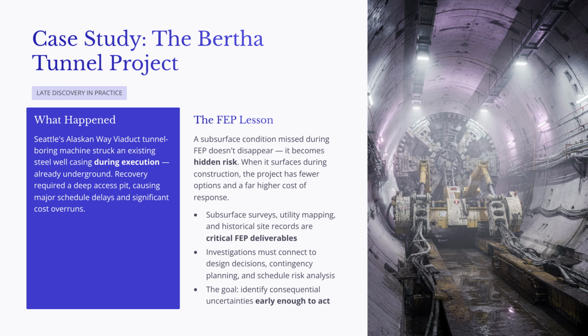A major disruption occurred when the tunnel boring machine struck an existing steel well casing during execution. At that point, the machine was already underground. The issue was no longer a planning problem. It had become an execution crisis. Recovery required extraordinary measures, including construction of a deep access pit to reach and repair the machine. The result was major schedule delay and significant cost overrun.